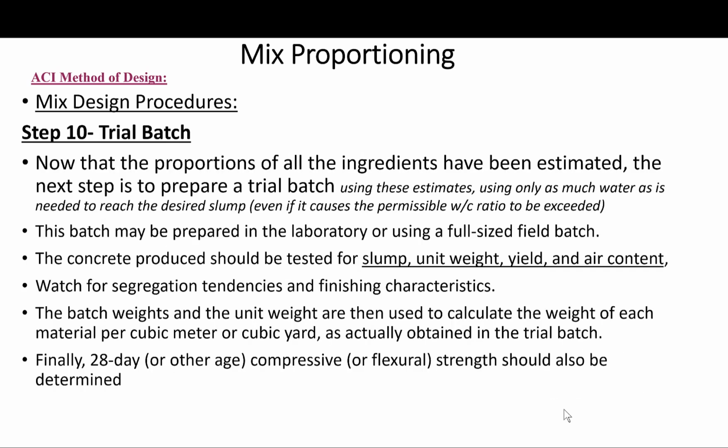Okay, step number 10 of the mix design procedure is a trial batch. So now, having estimated the proportions of all the ingredients, the next step is to prepare a trial batch using these estimates, using only as much water as is needed to reach the desired slump, even if it causes the permissible water cement ratio to be exceeded. So that's what we're talking about here. This trial batch is to fine-tune the mix design and make any necessary adjustments.